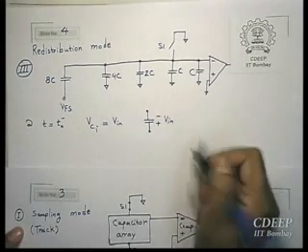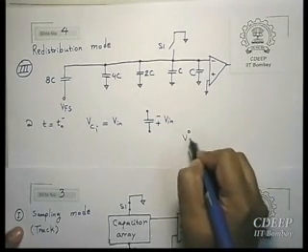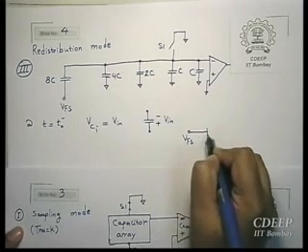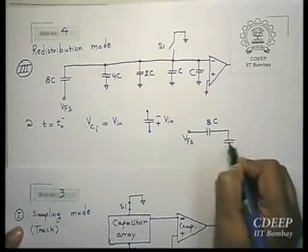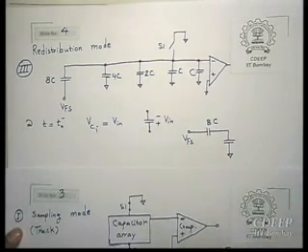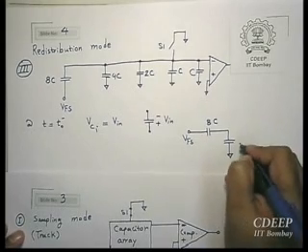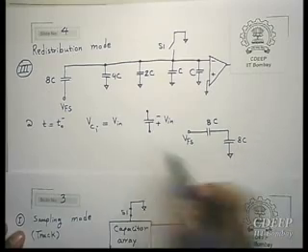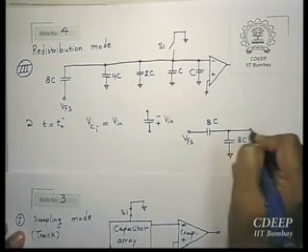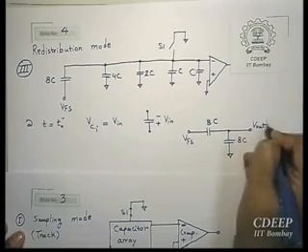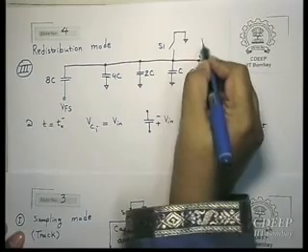The equivalent circuit, if I redraw it, will be like this. And this is the total summation of these capacitors, which is 8C again, since 4 plus 2 plus 1 is 7, plus the extra C. And this is Vout, which is going to the comparator. So this node is Vout.